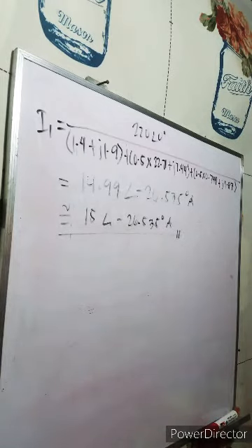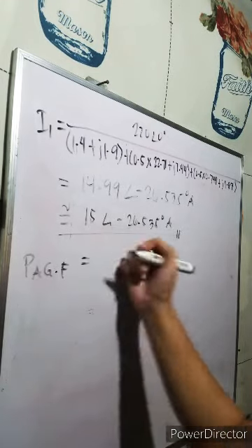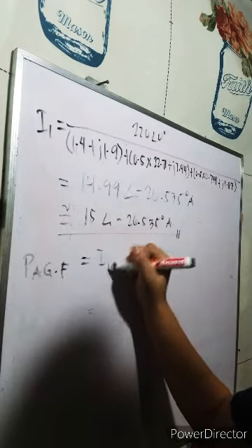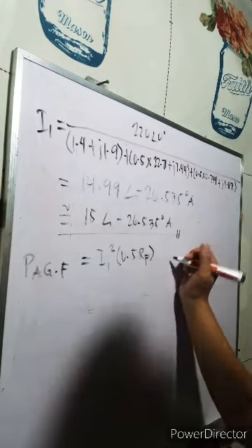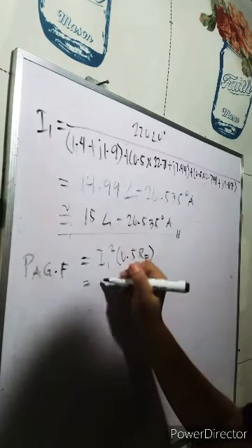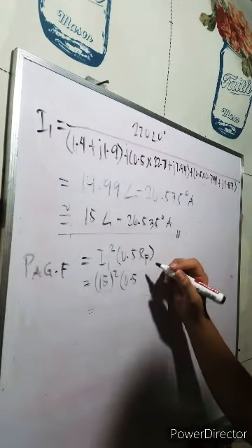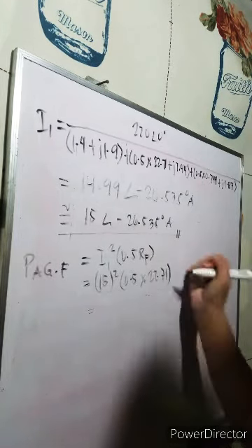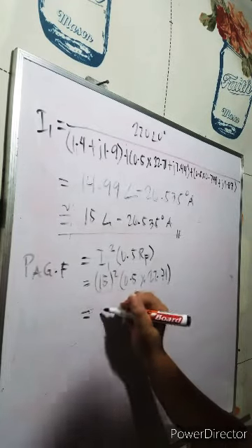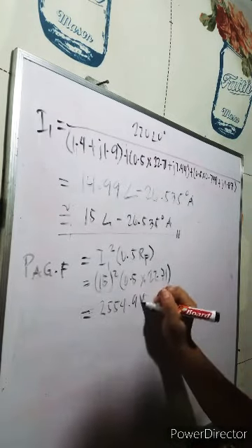From this, we can solve the following power. The forward air gap power is I1 squared times 0.5 RF, or 15 squared times 0.5 times 22.71, which is then equal to 2504.9 watts.